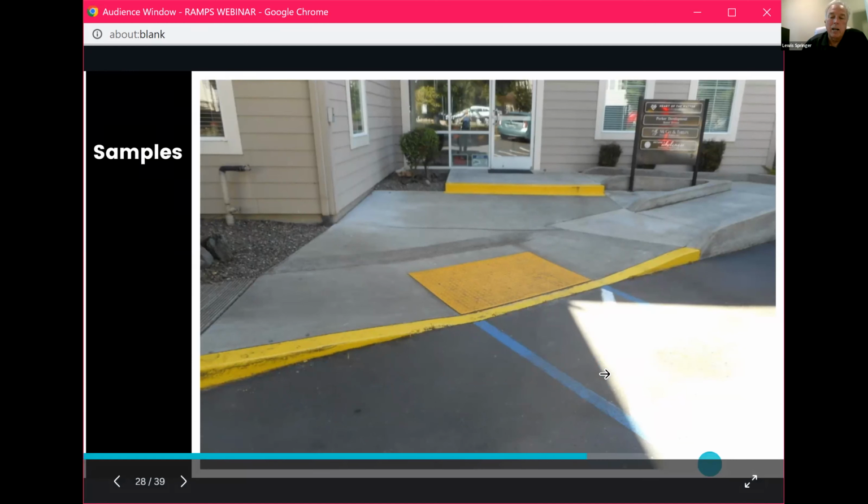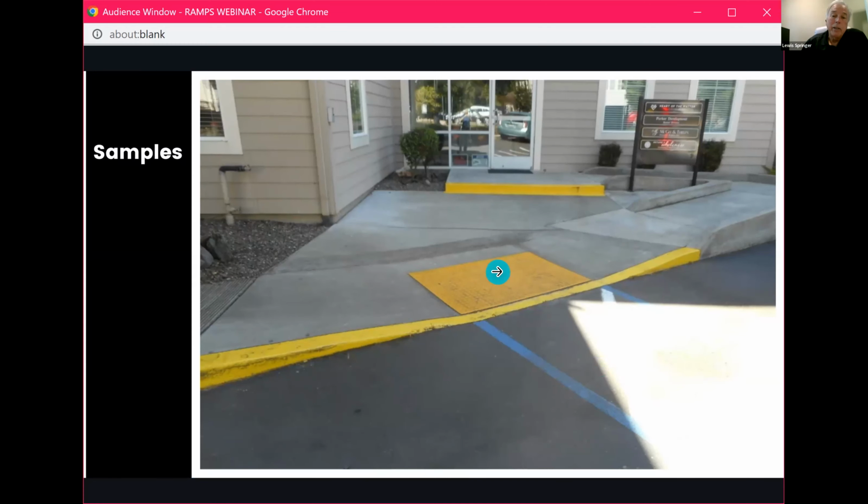So you come across the drive aisle and you meet this perpendicular curb ramp. Of course, the top landing sloped about 7%, and it sloped 7% all the way to the step going up to the door. As soon as you build this step, one step's considered a stair, so the step would actually require railings on both sides.